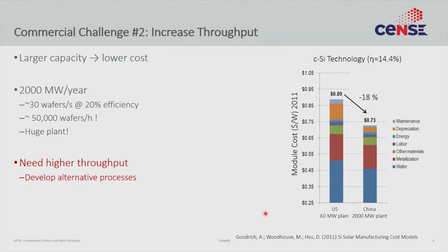Now, silicon solar cells cannot be scaled. In fact, if anything, you want larger and larger silicon solar cells. So absent scaling, what can you do? The only thing you can really do is make sure the process happens fast, right? So each step should take as little time as possible, and you should be able to push as many wafers as possible within an hour. And I can imagine if you have a series of steps, the slowest step then decides the rate at which you are producing.